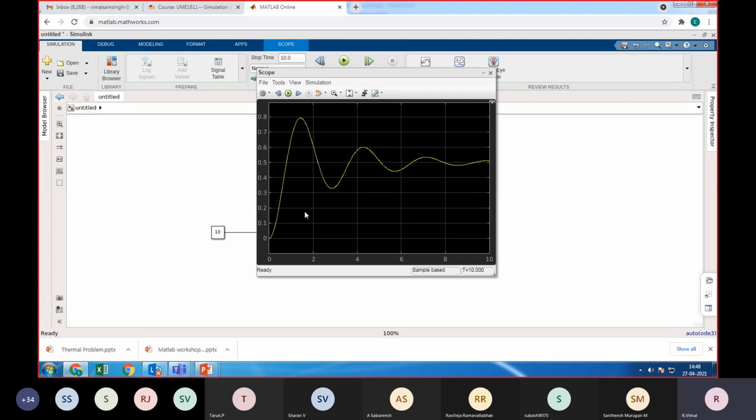How we usually do it is we create an ideal system, and for the ideal system we create a Simulink model and see that both are in sync. Then we try to replace these components with new components and see whether they are able to reduce this time, and whether we will be in a position to reduce this jump. So this is how we use Simulink.